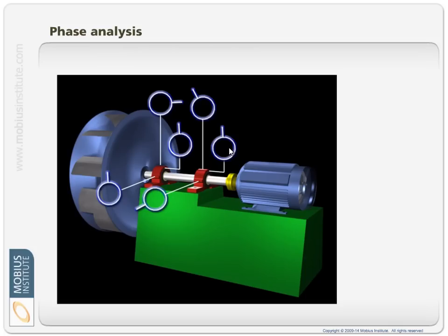The challenge with phase is how you measure it. Now, the simplest way is to have a 2-channel analyzer, carry that second accelerometer with you, because you usually just take single channel measurements on a machine. And when you suspect a problem, you put, for example, one sensor on top, one sensor on the side, and say, what's the phase difference at the running speed between these two locations? And if it's somewhere around 90 degrees, aha! Now we take one sensor and put it in the axial direction, another sensor in the axial direction here. And we say, what's the phase difference between these two locations at the running speed? They're pretty much in phase with each other. And so that's all you've got to do.